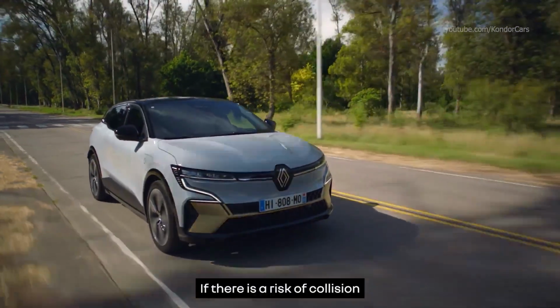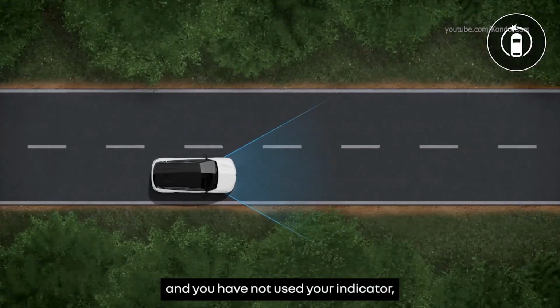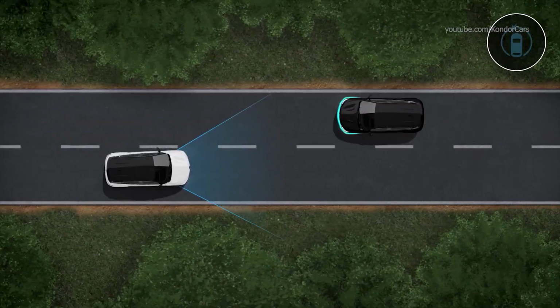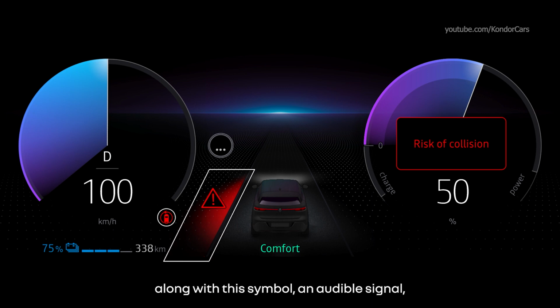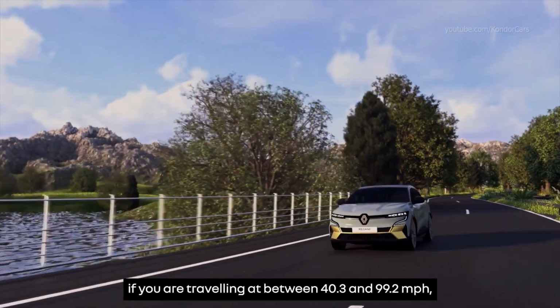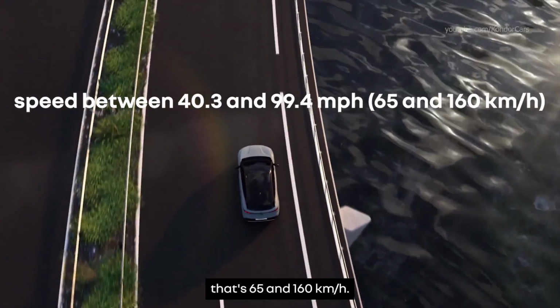If there is a risk of collision with an oncoming vehicle in an adjacent lane and you have not used your indicator, the system will correct your trajectory. This red indicator lights up on the instrument panel along with this symbol, an audible signal, and the message "Collision Risk." The system can detect a vehicle coming up from behind if you're traveling at between 40.3 and 99.2 miles per hour. That's 65 and 160 kilometers per hour.